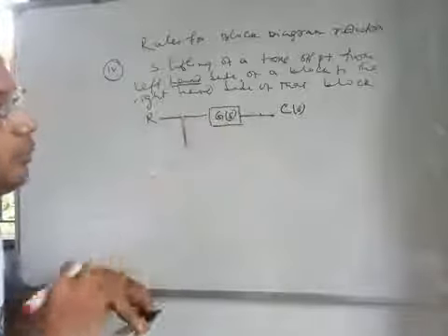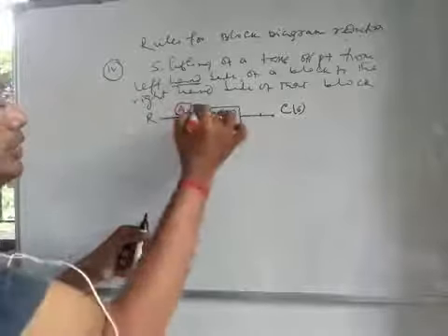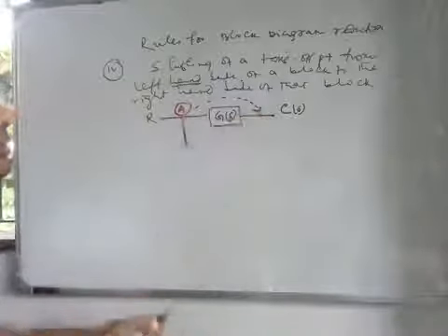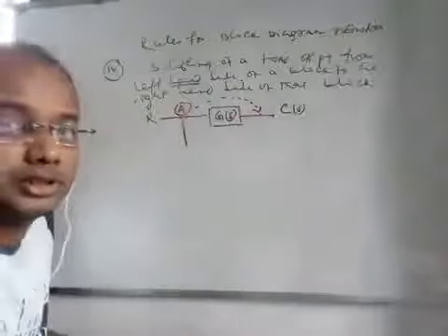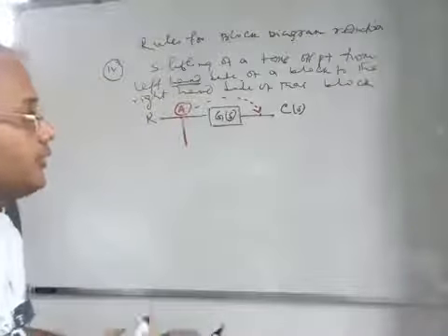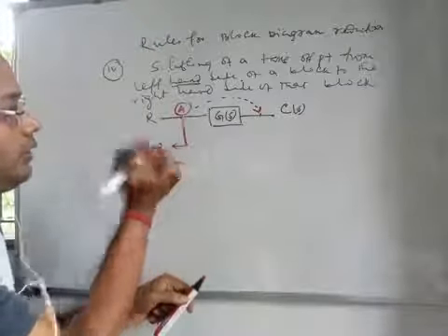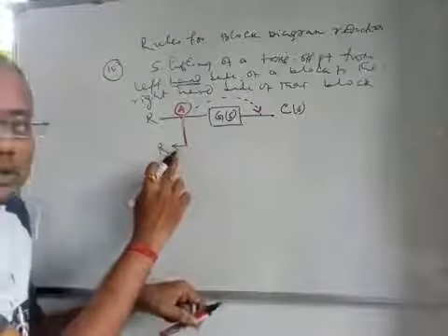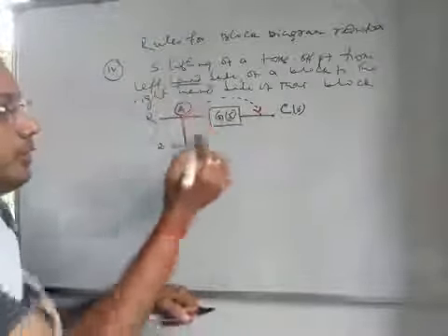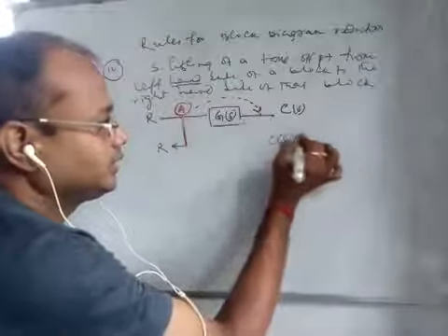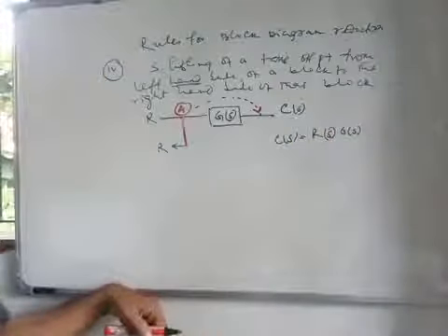So this is the point. Here there is a takeoff point. Now you have to shift this point. Maybe this point is say A. This is to be shifted to these positions. Once this is shifted to these positions, definitely there will be certain manipulations on the defined blocks. What will that be? First of all, this is your R, so takeoff point. What is the value of the signal you get? This is definitely R, because the R signal is what you are taking off from here. Next, you see C(s) is equal to R(s) into G(s). Fine, there is no problem.